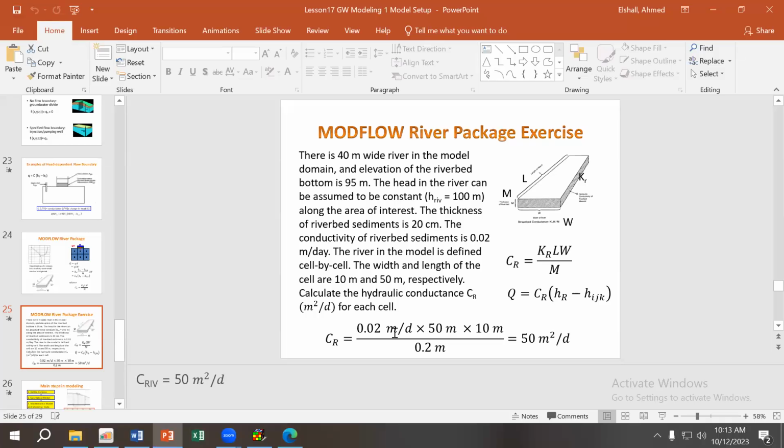These things you can easily measure in the field. If you are doing field investigation, you can get this value with different methods, and your hydraulic conductance could vary across your river. For example, like I told you, when I was in Ireland, this exchange between surface water and groundwater is not happening everywhere. It's only happening at certain locations. And you can find these locations very easily by heat tracing, for example, because surface water and groundwater have different temperatures. If you have something that can measure temperature, you will see, okay, here is a different temperature, here is a different temperature.